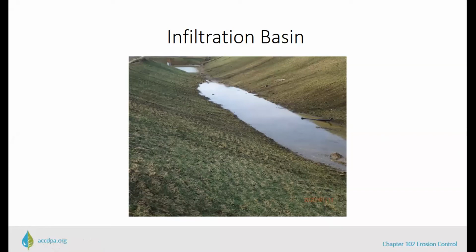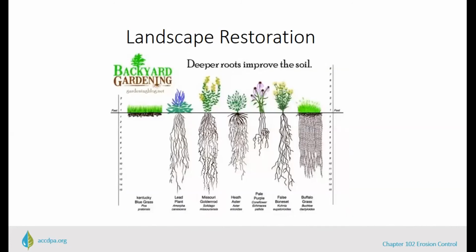Remember previously, all that stormwater collected and went directly into a heavily damaged small unnamed tributary. Now there's a 2+ acre heavily vegetated infiltration basin that collects it, settles out pollutants, and discharges at a controlled rate.